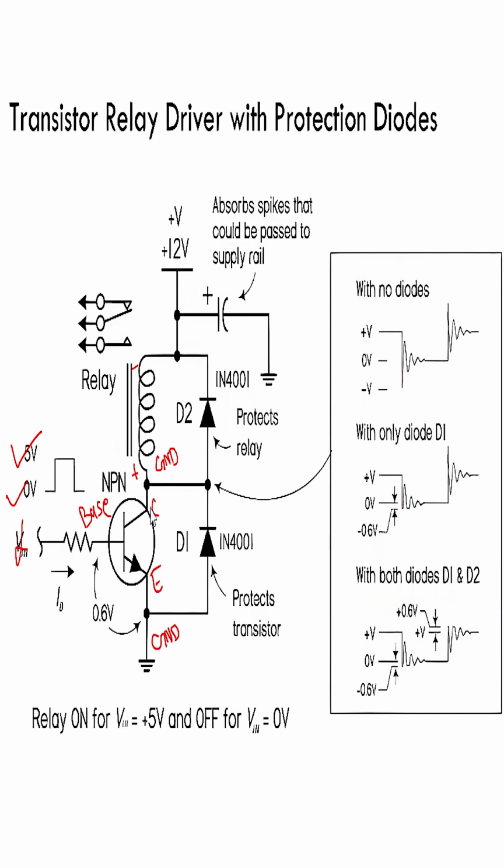Also, because this circuit is switched off, there is no possibility of current flow, so the voltage spike will be high, and the generation of negative voltage on the collector side will be high. It means a high negative spike will be created here. That can cause damage, because the transistor was closed, but this positive spike is insisting that it open. So that ground and that negative spike is created. As you can see, this negative spike can damage this NPN transistor.